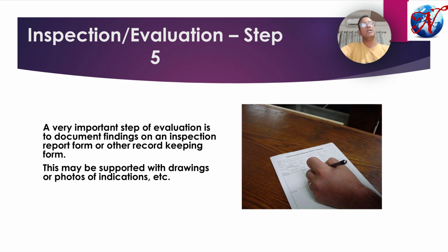So green to yellow bleed-outs will be there in fluorescent dye, and red indications will be there. During the inspection or interpretation, the inspector needs to have the ability to identify whether the defect is true in nature or false in nature. Any kind of geometrical indication will be considered a false indication. The rest will be considered a true indication.